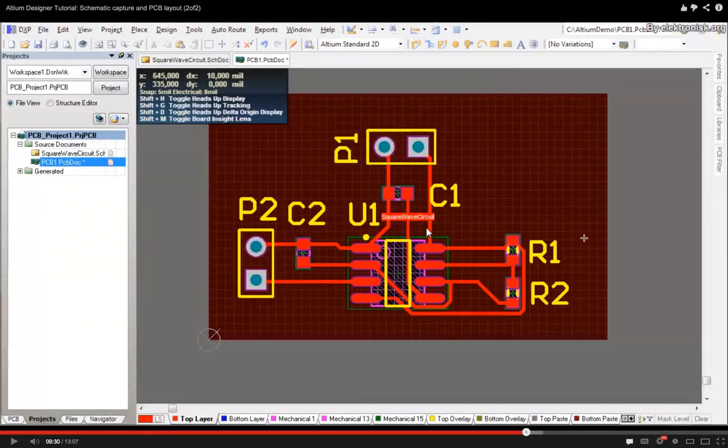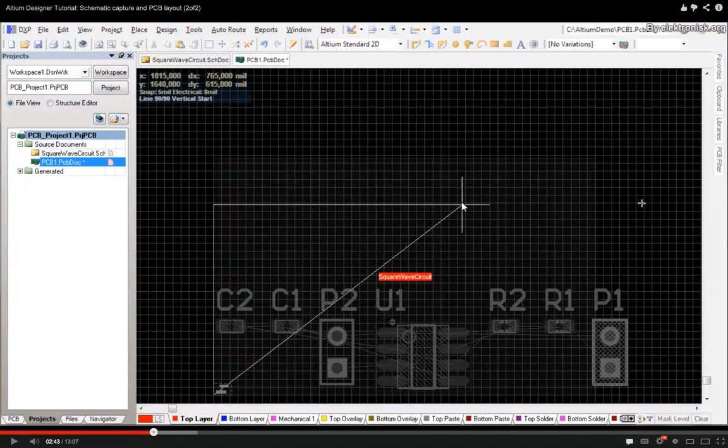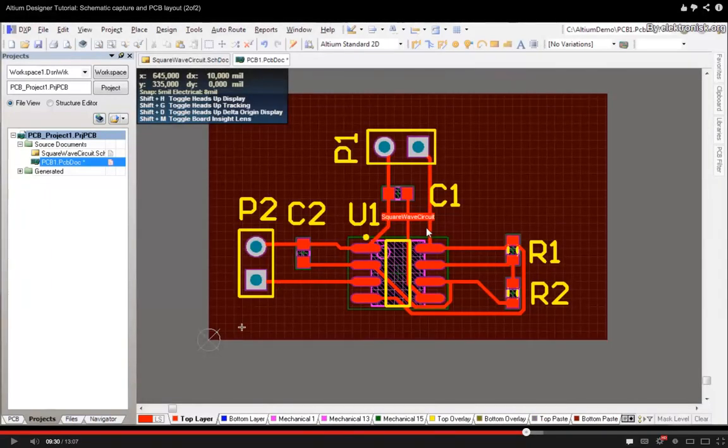You drag it to one of the corners you want, and then you click it, and you drag down to the last corner, and you right click it, and then you will end up with your board shape like this, with the other areas in gray. So this is the board shape that we have, and then you can start locating your components, depending on where you want to put them, and depending on your restrictions and your conditions.